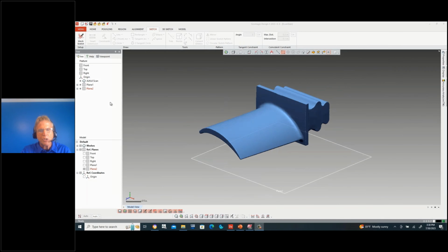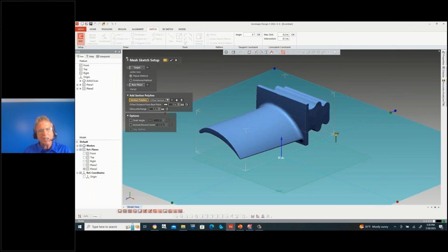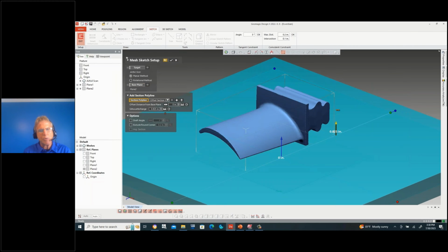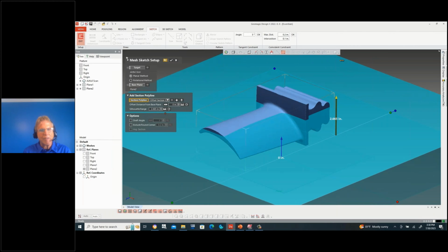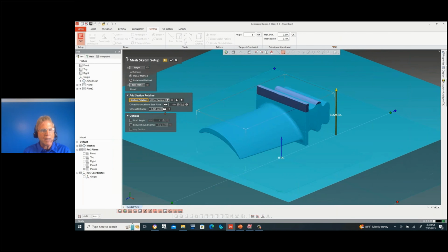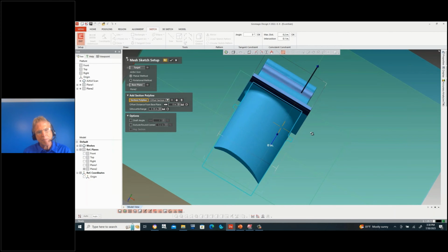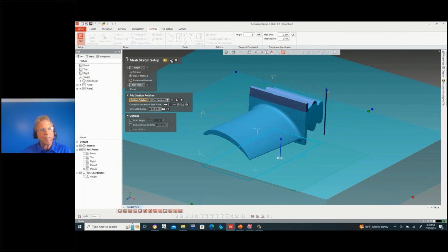sketching. So here in Design X, if we say, let's create a mesh sketch on this plane, we can actually thicken the plane out to a volume. And then wherever that volume passes through our part, we can pick up the silhouette edges of the part and volume intersection. So here, I'm most interested in picking up the edges of the blade, which I do have from that volume.